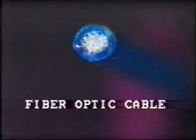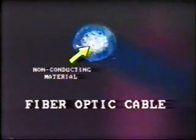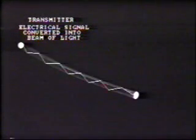Another communication channel which is rapidly being introduced into the power system is that of fiber optics. In this arrangement, the signal is transmitted by light waves traveling through an optical fiber. The fiber is made of non-conducting material, so it cannot provide a path for electrical signals. At the transmitting end, the electrical signal, perhaps a tripping signal from a relay, is converted into a beam of light. This travels down the fiber like this.